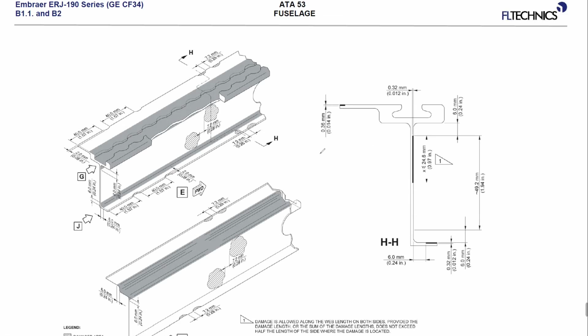According to the standard practices, we have to use plastic or wooden scrapers to remove the sealant so we can remove the panel. It's not enough if we only remove the screws. We also have to remove the sealant.